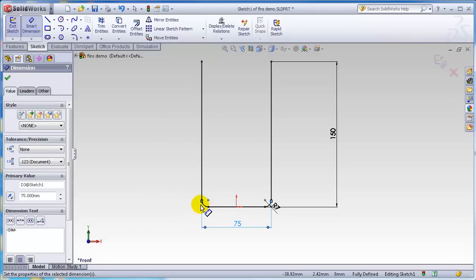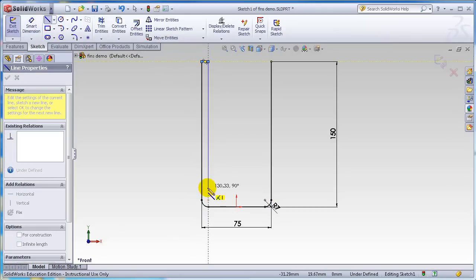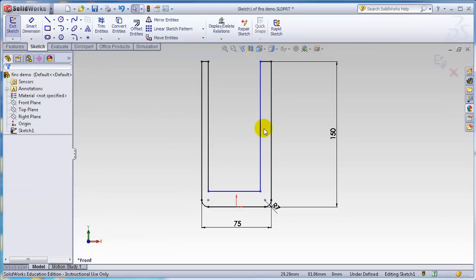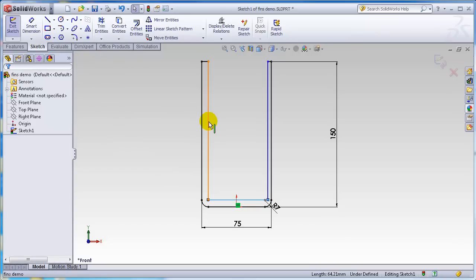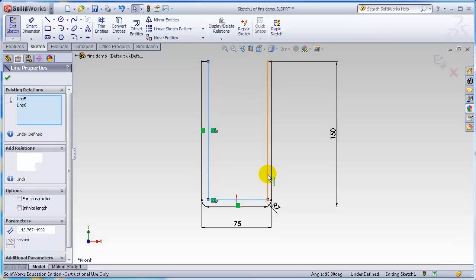If I wanted to take a little bit more control of the shape, then I might come in and do some things like this, and I'm going to undo these shortly, but add some thickness to it. Now I have a closed figure, and then I could adjust some of these things to give me exactly the profile that I want, including putting fillets in this top part of the figure. I'm not going to do that because I'm going to let the extrude thin feature take care of that for me.